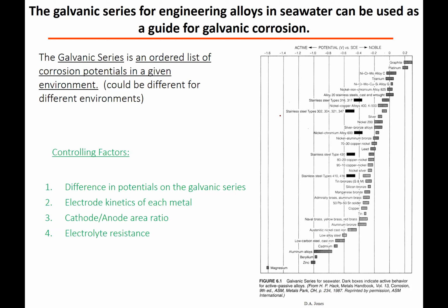So before, I talked about just looking at the thermodynamics and not looking at all at the kinetics. Well, the galvanic series takes a look at the kinetics of a system, and you may actually see a reversal in which materials are going to be more active or less active in this series. Okay. And so what you typically see for a galvanic series data table looks like this, where if you look at the potential, they're listed this way.